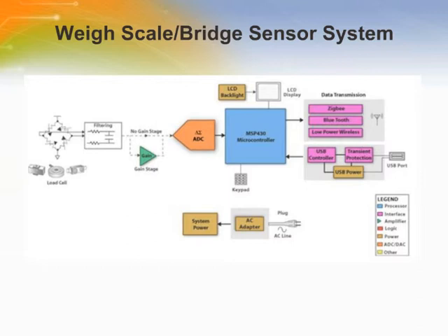Also, many bridge pressure sensors have a nonlinear output with applied force. Here, the accuracy of the amplified input signal must be guaranteed over years of operation. A zero-drift instrumentation amplifier, such as the INA333, easily meets these stringent requirements by achieving an offset drift of 0.05 microvolts per degree centigrade.